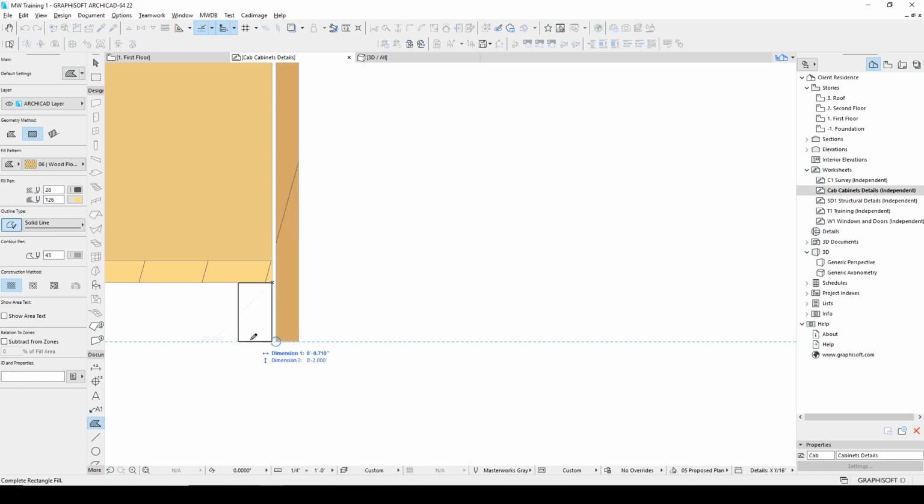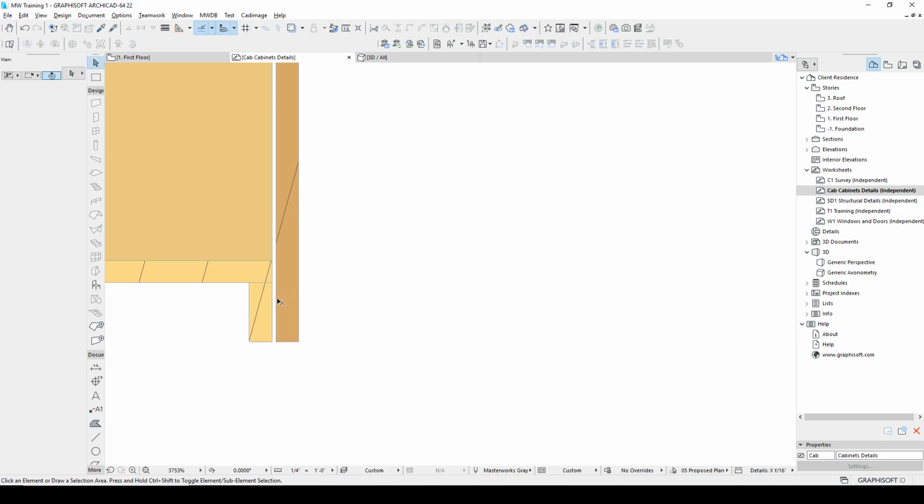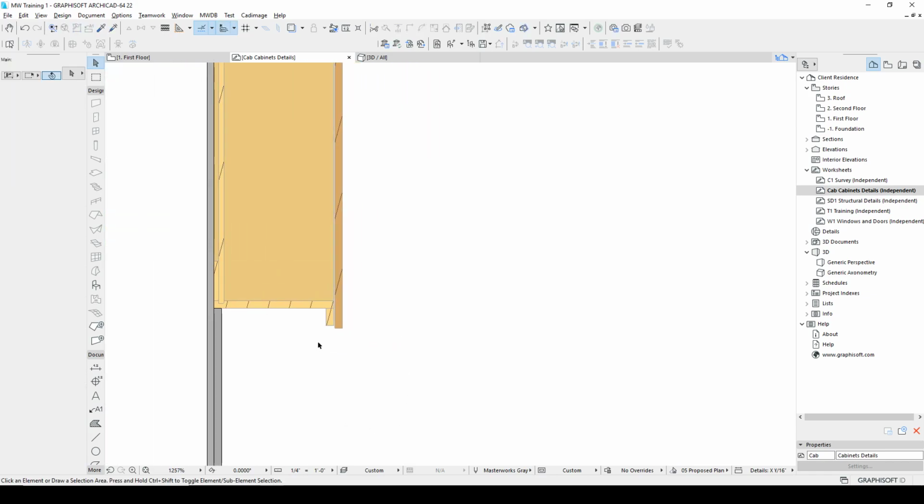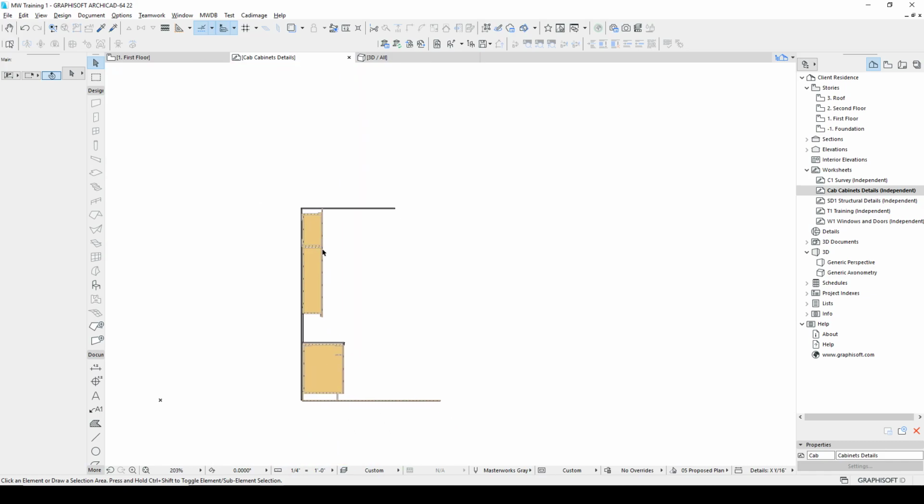From that point, I can let go of the keyboard and then I can just, in the dimension 1, put in the 3/4. And now I have a light rail here, and maybe it wants to go up 1/4 inch so it doesn't get exposed, and I have a place to put my light. So again, just keep layering and layering and layering. And these become fantastic to work out all of the wonderful details that make a job so important.